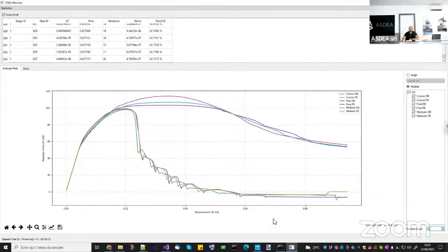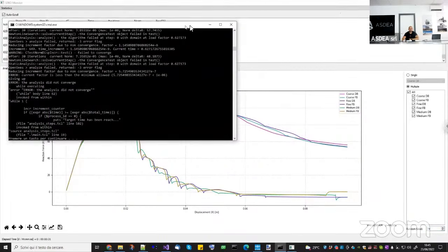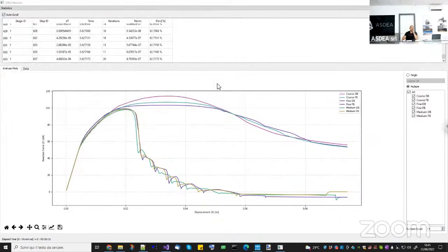Okay, now here, up to here, we have, yes, a convergence problem also here. Perfect. So once again, up to the peak point, everything is fine. The solution is the same. There are small differences, but it makes perfect sense because the example that I did before was a constant state of deformation, so even one single element can give you the exact solution. Here it is a bending problem with nonlinearity, so it is not the same thing. You will see a small difference, but the solution is stable. Actually, as you refine the mesh, they go to the same solution.